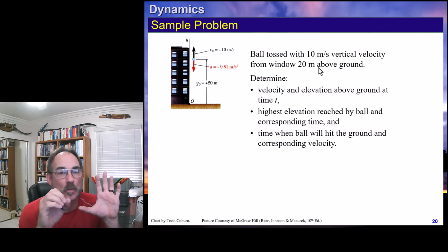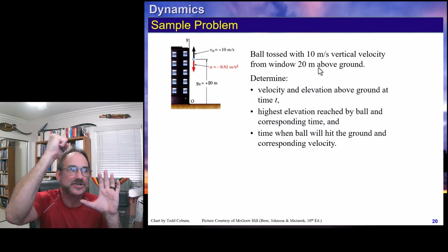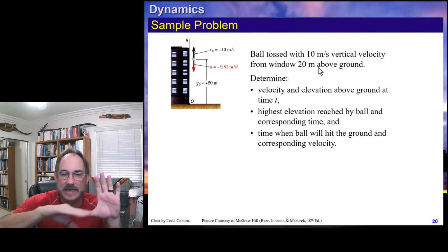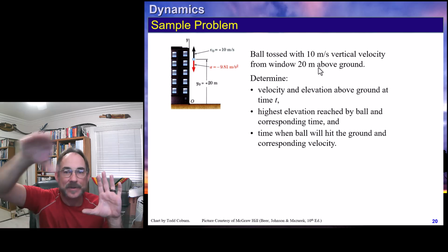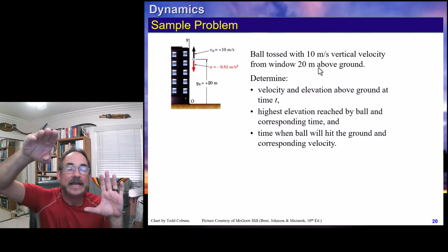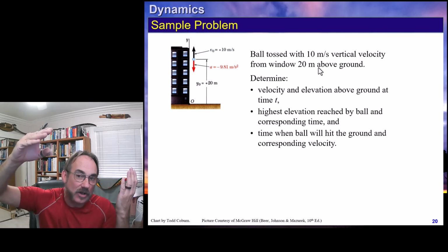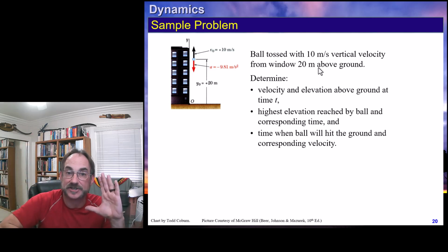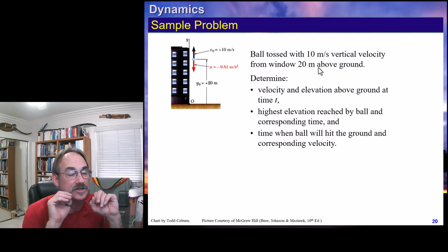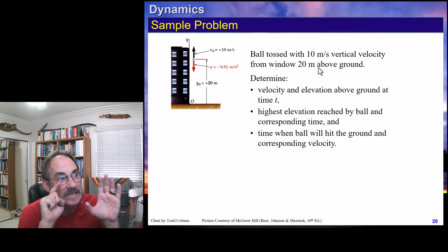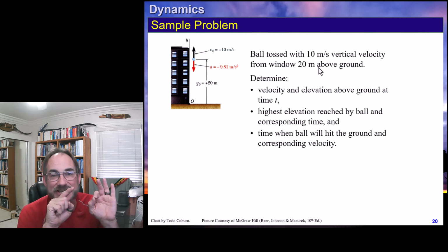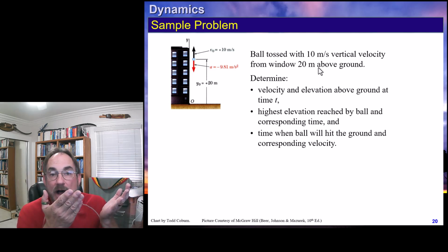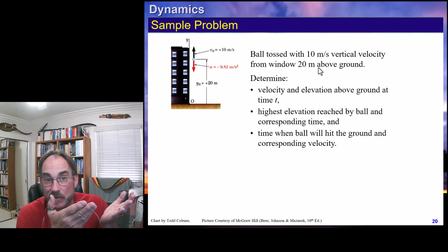This picture says we're at a position 20 meters off the ground. Our origin is down here at 0. That means s down here is 0, and position s up here is 20. Instead of calling our position s, we can use y, since we're talking about a vertical position, rectilinear motion in a vertical direction. So we can say y initially, or y of 0, is 20. Eventually, this ball is going to hit the ground, so y final is going to be 0.